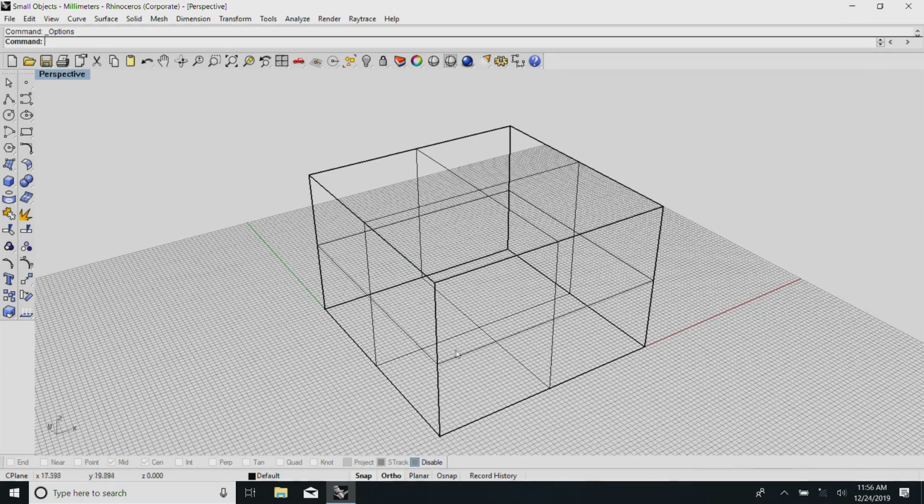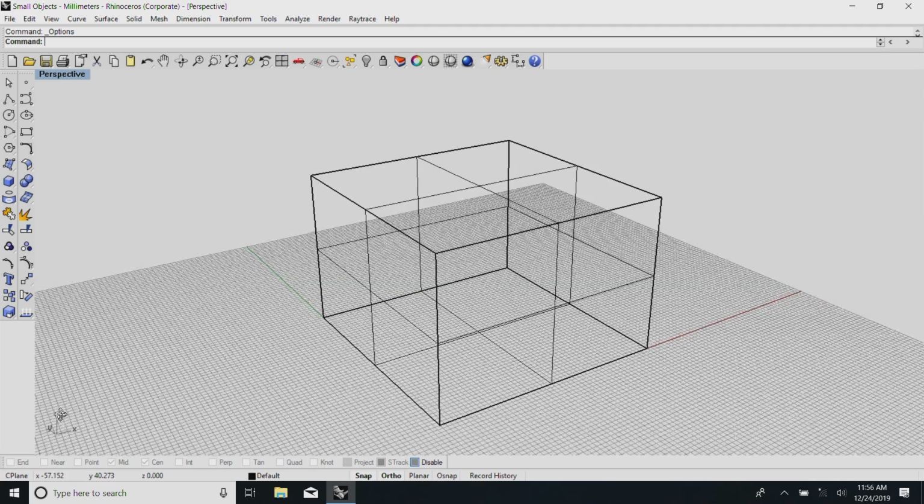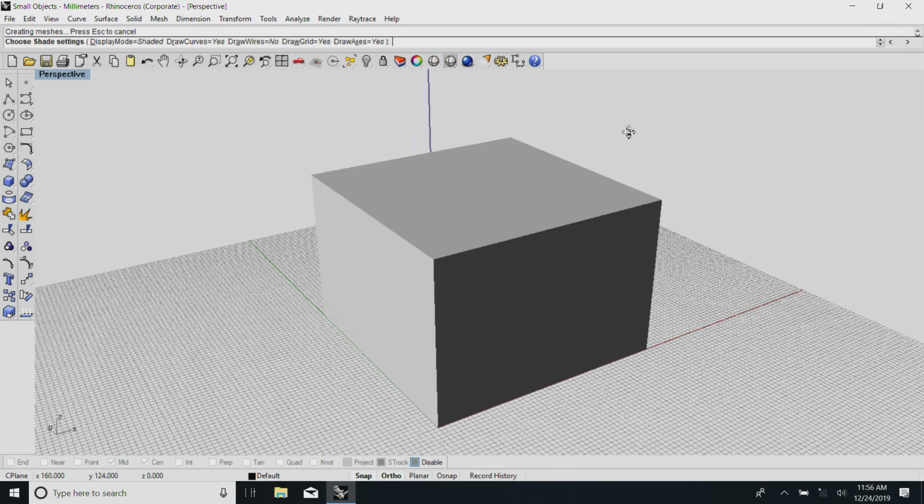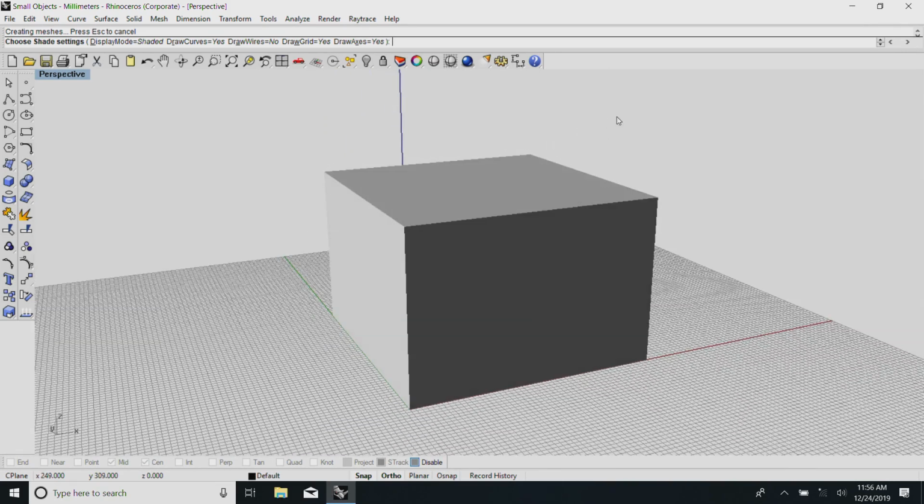At the corner, if you see, I have this world icon axis. I have x, which is conventionally left to right, y is front to back, and then a z quadrant which is top and bottom. So, if I now put it in this mode, I see that I have this nice thing sitting here. Now, I need to make a groove which is 31 mm wide and 11 mm deep.